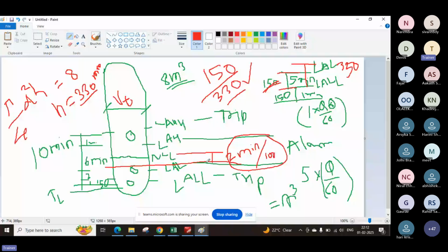Generally it is based again on what kind of liquid you are getting. If you have a very high volumetric liquid, suppose you have a vacuum distillation column, next to that there is a condenser followed by a separator, like a three-phase separator or what we generally call a reflux drum. So in those cases a vent nozzle is connected.